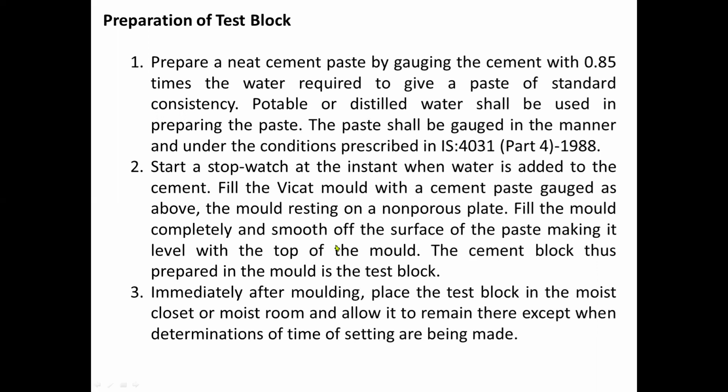Immediately after molding, place the test block in the moist closet or moist room and allow it to remain there except when determinations of time of setting are being made.